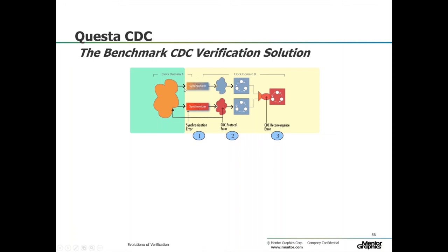If you're passing a bus, now you can't just put those single bit synchronizers. You have to get a little more complex. Maybe you put a mux and you say, I'm going to hold the value in the receiving flip-flop until I get the signal that it's safe to sample, et cetera. Well, now you have a timing protocol. You have to make sure that bus is not changing the entire time that control signal takes to get over, get received, and go away in the other domain. So now you have a timing protocol.